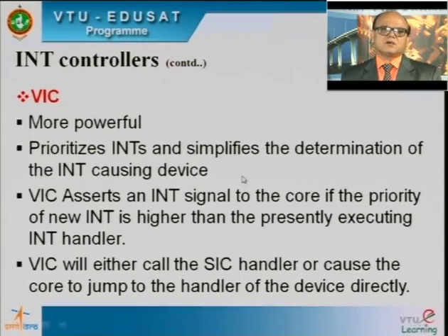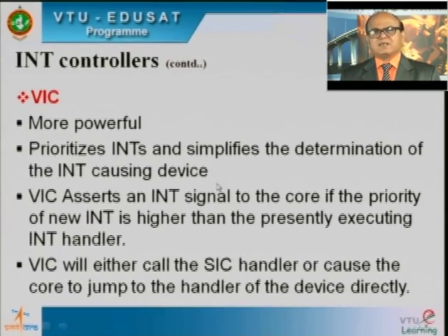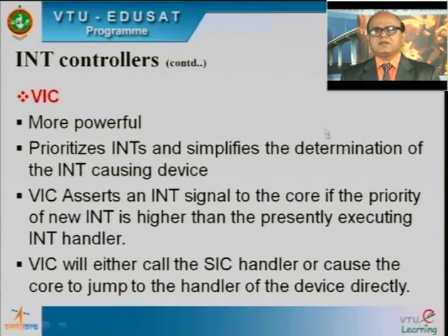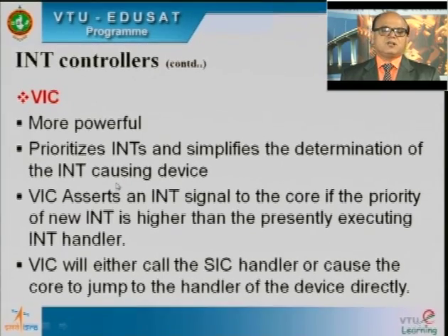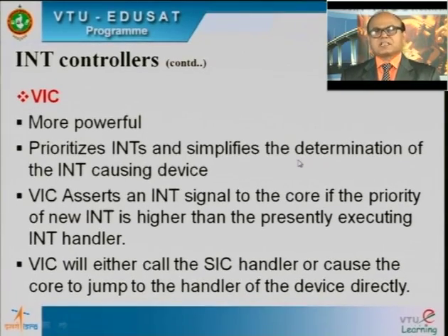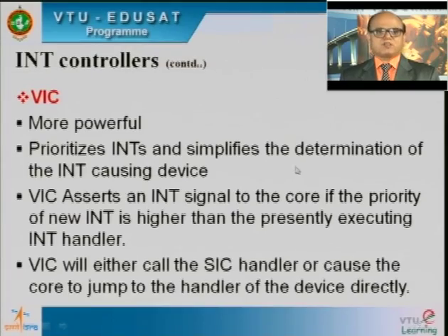So the controller's job is simplified, and therefore we say vectored interrupt controllers are more powerful. The VIC prioritizes the interrupts and simplifies the determination of the interrupt causing device. The identification of the device causing the interrupt is made very simple in the case of vectored interrupt controllers.